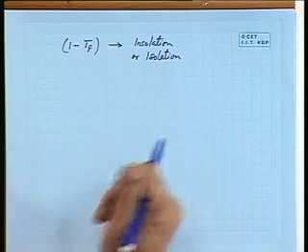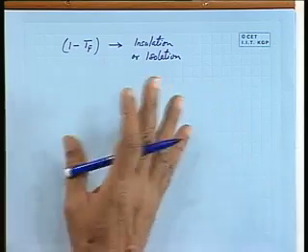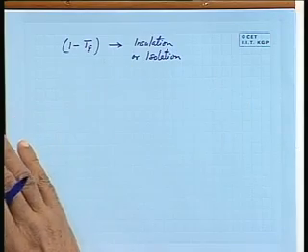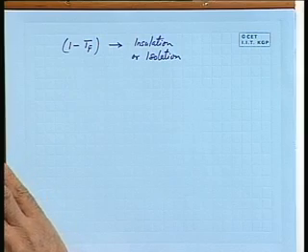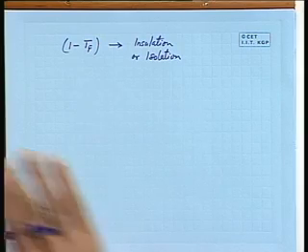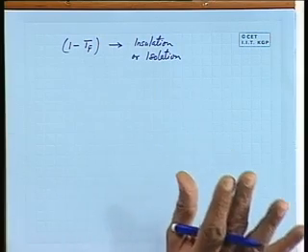At the same time, the motion amplification of the equipment can be measured by comparing the maximum equipment displacement to the static displacement under unbalanced static force.